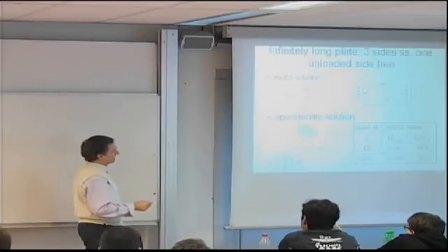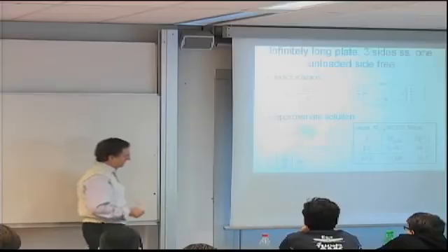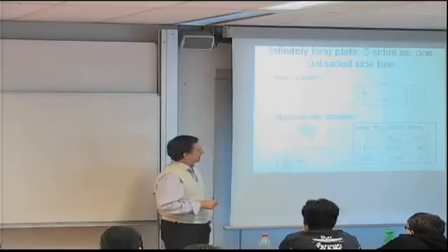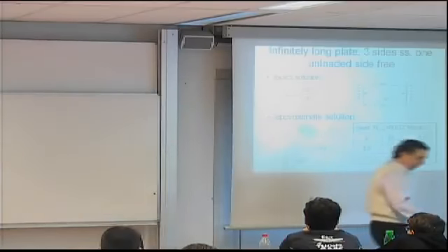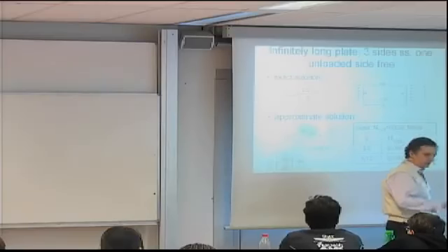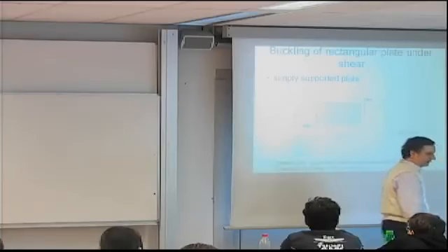But luckily we have a residual term that's d12 dependent, which looks like this. So for a given case of a D matrix shown here, for an infinite plate, we get a 46.9% error, or for lambda 5 divided by 12, we get 12.5% error. So this is a good approximation if you have the right value of lambda. In this case, it looks like the right value is something like 5/12, in fact, a little less than that would be even better.